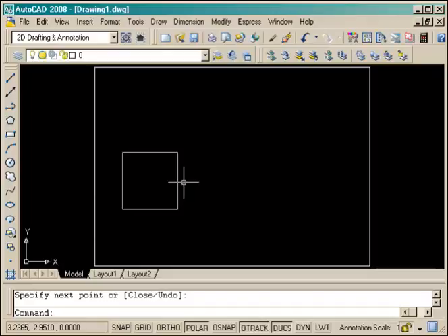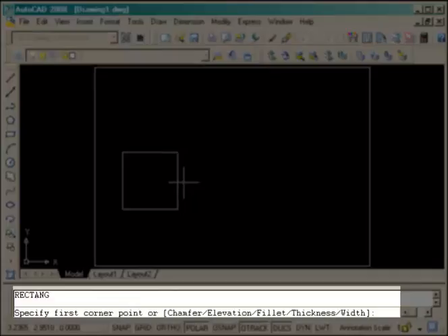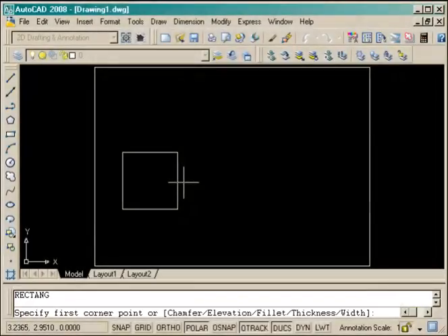The second one, just to the right of it, we're going to use the rectangle command for, and what that needs is 2 points: a start point for one corner and then the point for the opposite corner. So we start the rectangle command by typing in REC, and the starting point in the bottom left corner is 4.5, 2.